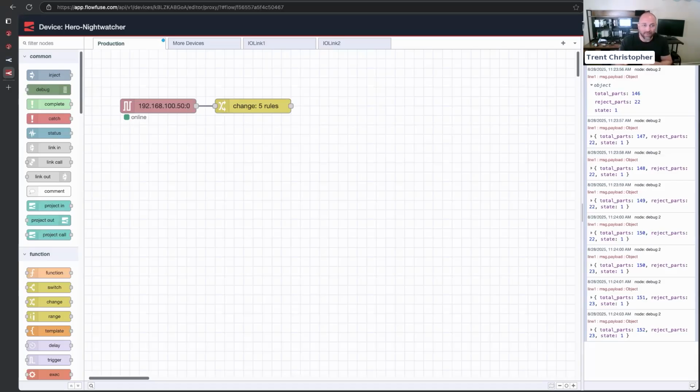You would still need a connector though. So a Rockwell device PLC is going to need something to connect to get that data to Grafana. For the most part, Grafana doesn't have a connector to Rockwell. So I may be a little bit wrong there. Maybe somebody knows of something, but I haven't seen it. It's not built in. Maybe a community has built one. So I recommend trying both, and you can combine them. So you can start to use a database. You could use an MQTT broker, and you can link them all together and start to see data in both dashboards.